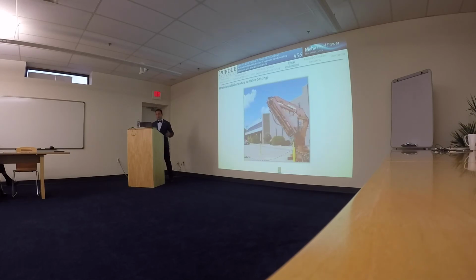And this is the section about the energy consumption I told you in the outline. So of course, this dynamic behavior is not something that you find in commercial machines. This is something we did on our machine in order to show energy saving potentials. And in particular, as I said about the counterbalance, they greatly affect the dynamic response of these machines. So what I did, I replaced the original counterbalance of the machine with some adjustable counterbalance, and I tried to evaluate how much is the effect of this